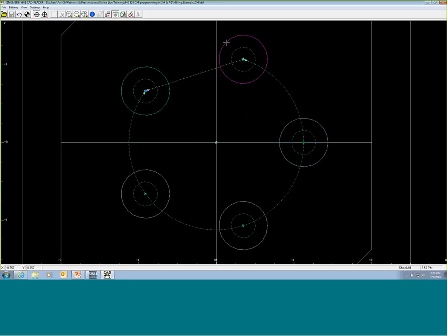And now you're going to pick each hole, and the order at which you pick them is the order at which it puts them out. So that same scenario, it's going to be the exact way it drills them. If I do a little zigzag pattern here, then it's going to drill that exact sequence that I see, starting with the first one I picked, going to the last one. And then I want to make sure when I'm done picking, I click End, and now it's stored. And you see I can't pick anything else anymore. It's stored these locations. So in this scenario, I need to shove them into a part program that already exists. We've already started putting some information.